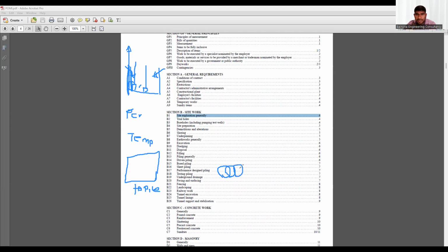They do it like this. The male pile will have reinforcement, the female pile doesn't have reinforcement. One of them will have reinforcement here, the other one is just mass concrete, then the next one will have reinforcement here. So this shoring is called a secant pile.